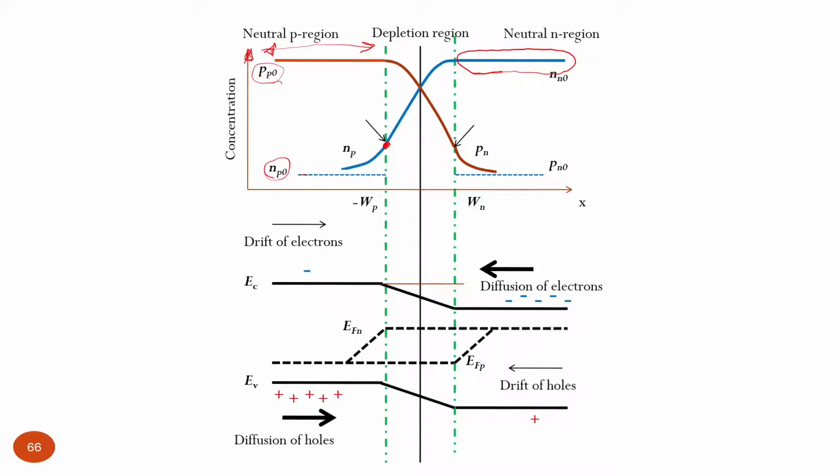And then, because of this compensation and recombination, their concentration drops, approaching the equilibrium concentration of minority electrons in this p-type region. So similar happens here. It is all kind of shown already with the Fermi energy level, but it's nice to reveal this in terms of the concentration of charge carriers profile within the p-n junction.